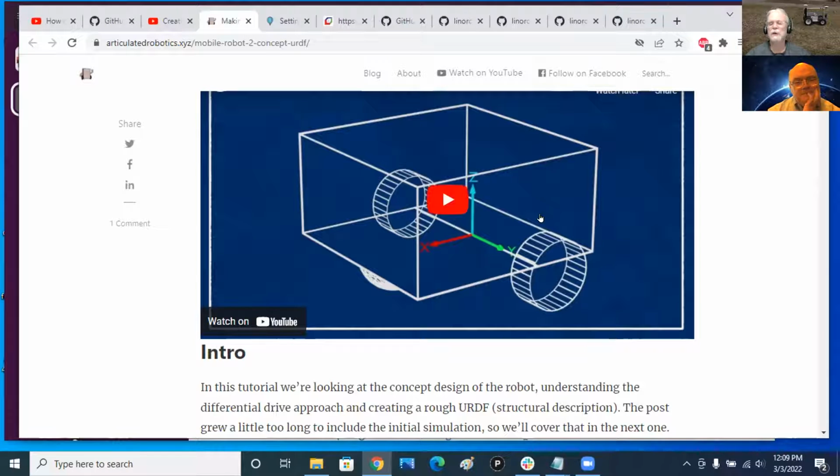So so far in the examples, they've just been showing a little slider on a tool they loaded in, and by moving that slider back and forth, you can watch it set the rotational angle of that wheel, but you can't actually drive it that way. If you had it in, say, Gazebo and did that, if you turn the right wheel, with the left wheel and the right wheel, what it's going to do is turn the other way.